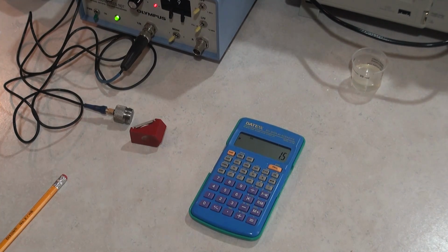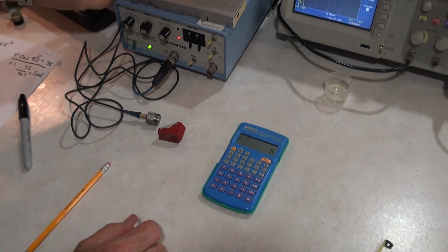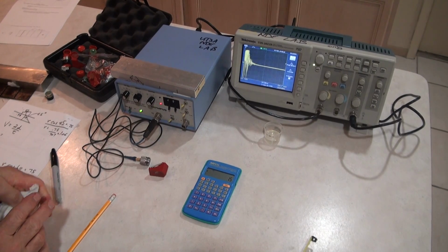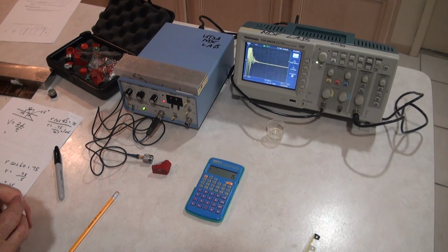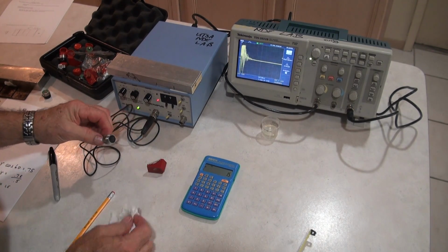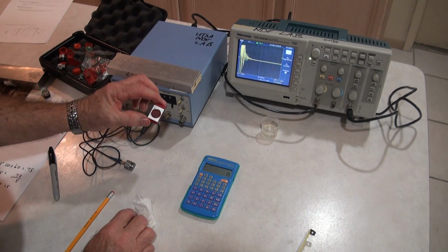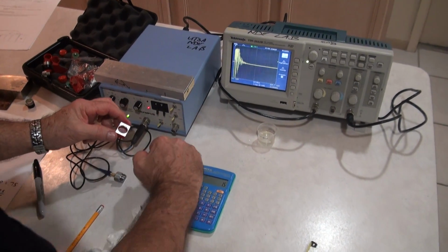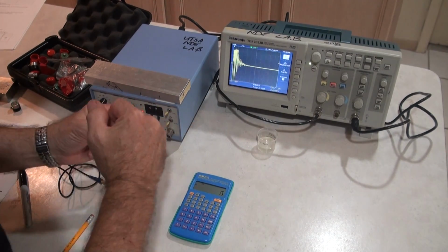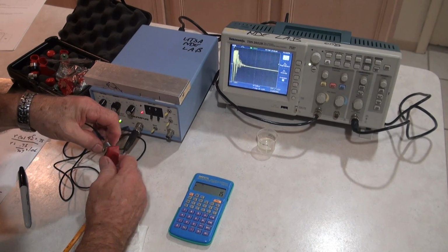Okay, so now we're going to do the shear wave angle beam inspection, and you can see I had that same aluminum block, but now we're going to look at it with angle beams, and by using Snell's law we can get different angles. And so the first thing we need to do is have a wedge, and that's what that wedge is. I think I showed it to you the other day. So again, we're going to have to couple the transducer to the wedge. Okay, I'm going to screw the transducer onto the wedge.